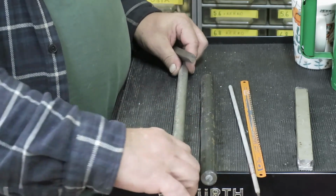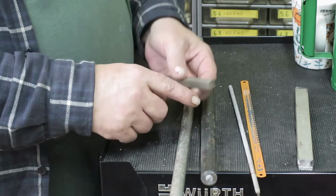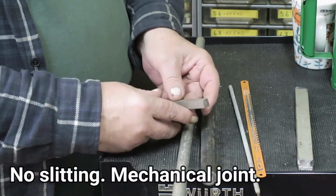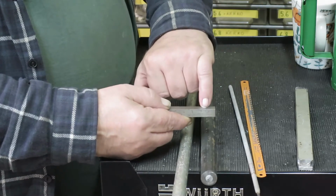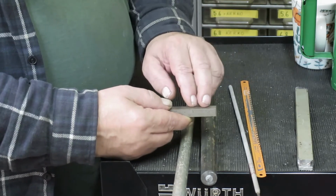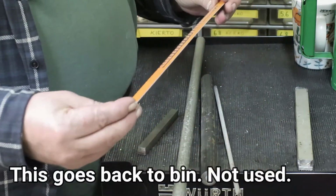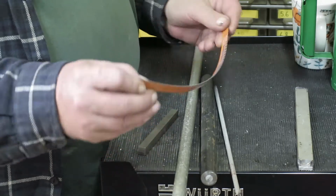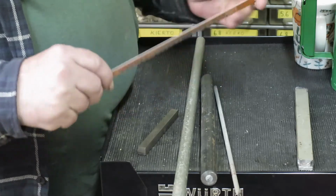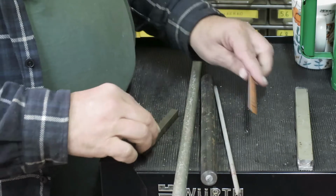And then there will be a flexure. I mean, it will be cut off, and then I will slit a very thin slit with a slitting saw on both pieces, and then I will use this. You know what this is? This is just a hacksaw blade, and this one is a really good flexure. Actually, it should do the trick.